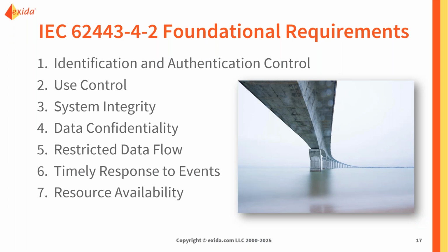If we think about IEC 62443-4-1 as the standard guiding our development lifecycle, 4-2 is then the standard that defines the specific security capabilities to help implement that defense in depth approach. It provides multiple protections to limit the likelihood of unauthorized access to a device through user access control, limit the probability of the data or system integrity being compromised, and limit data flows and connections to the devices.